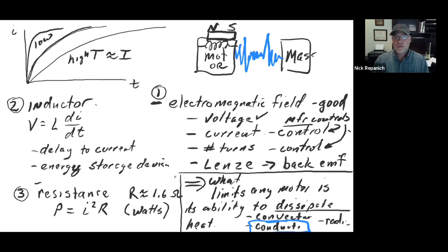So if you look at most motors, they have that really nice flat face. That's the heat conduction face. If you think about it, there's no reason for them to have this big flat face. Normally they could just have 4 tabs to mount it to, or just put a strap around it. But no, they give you that front face. That's for conduction. So when you design your stuff, you design a motor mount that's designed to pull that heat away and get it out of the motor.